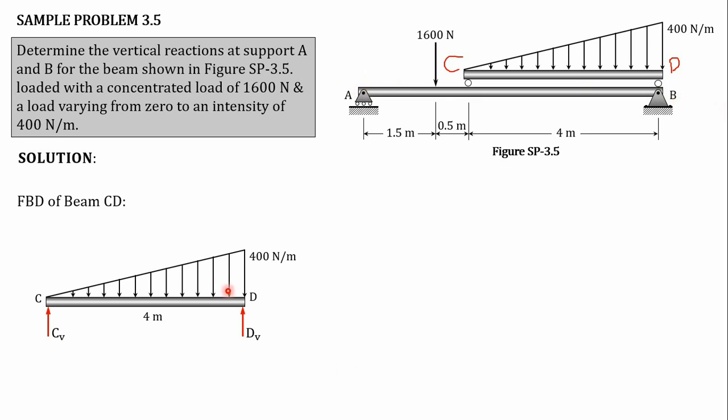Okay? So, unang gawin natin dito, class, isolve muna natin yung resultant force ng triangular distribution load na ito. So ito yung ating P, and we know that P is equal to 1/2 times 400 times 4. That is the area of this triangular load, and that is equivalent to 800 Newton. And then, what is its location from this point? Since that P will act at the center of gravity in this section, therefore, that is 2/3 of 4 meter. Okay, check ko lang, class.